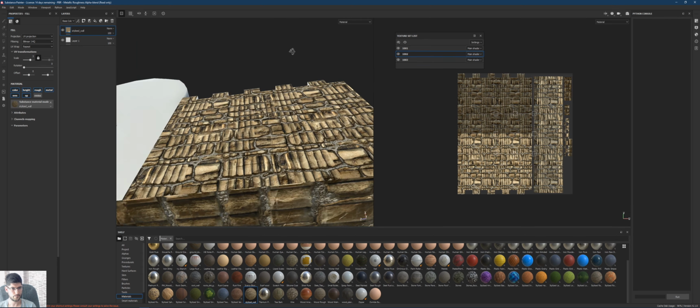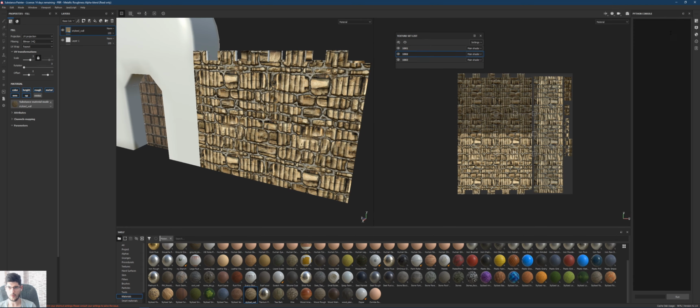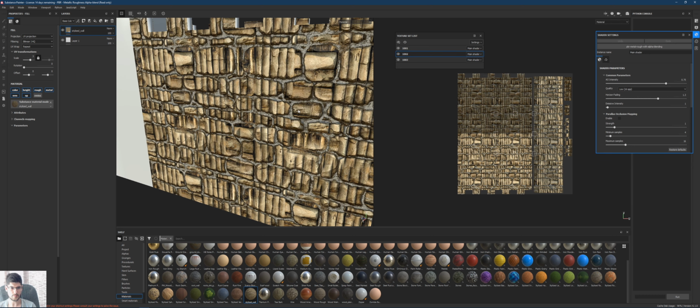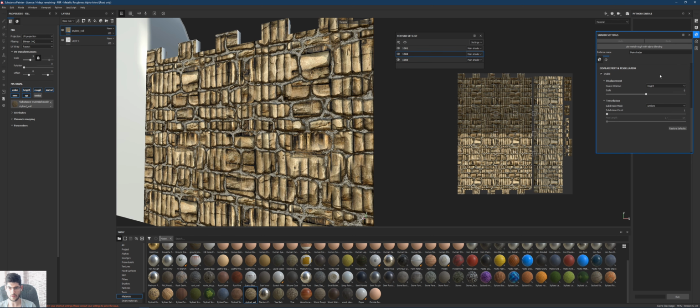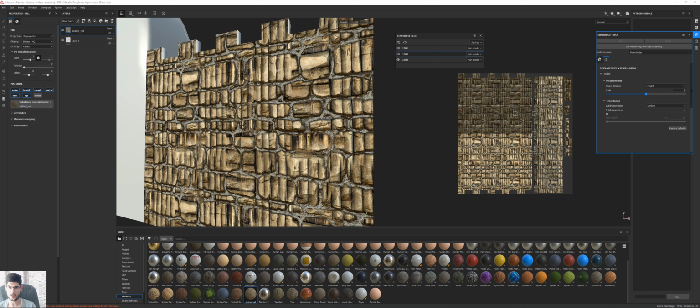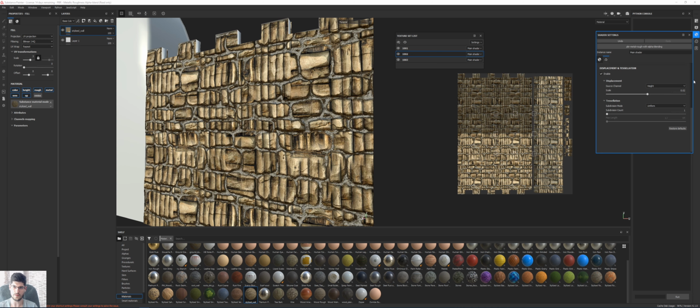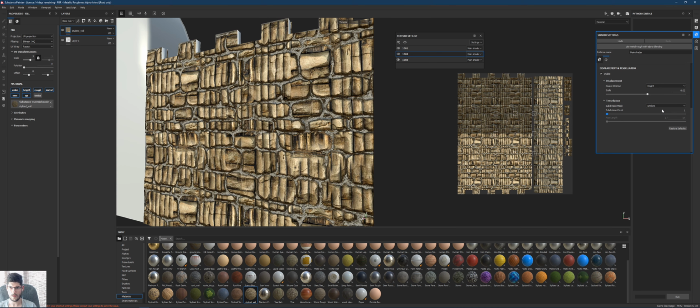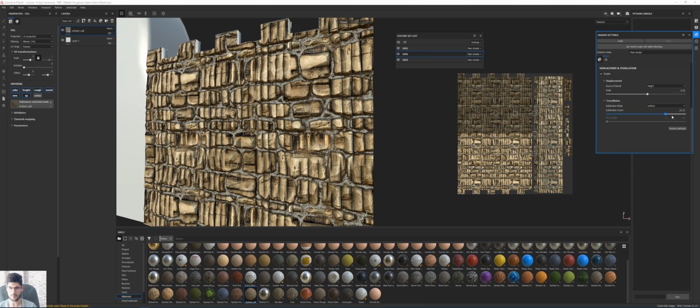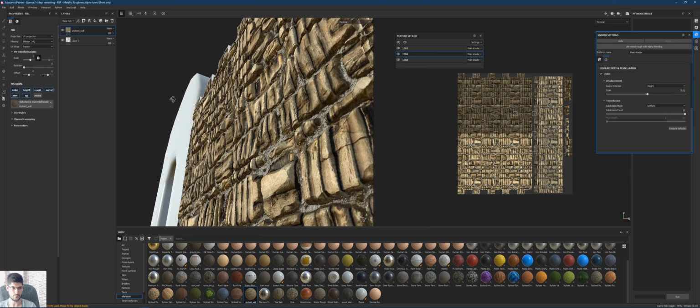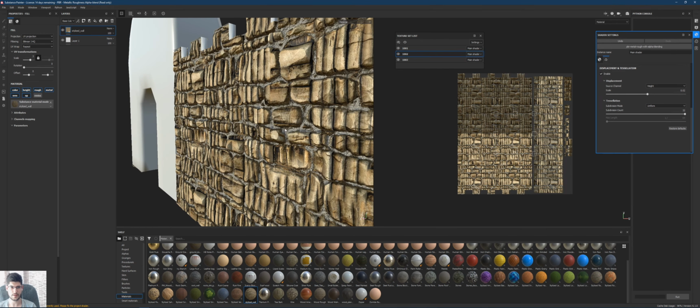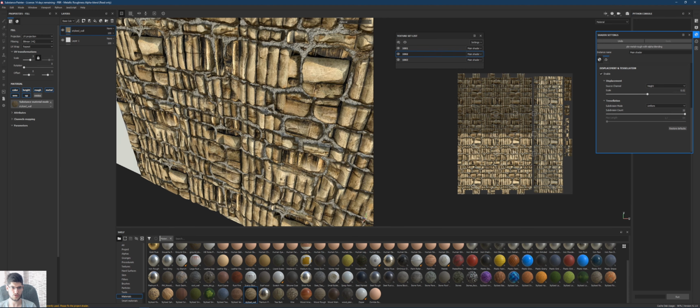Okay, now what we want to do is start adding our displacement mapping. So I've just opened our shader editor. I'm going to set the height information to 0.02, and I'm going to increase the subdivision count to 32. This means that we've tessellated this mesh now, although it doesn't show you in the wireframe.